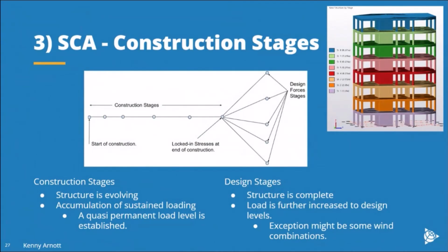So starting with this concept of construction stages and design stages, which may be unique to our software in that terminology. So the construction stages, got a sort of timeline view here. The construction stages are dealing with the evolution of the structure. So we're building it up floor by floor till we've got the structure complete. And at the end of that construction, we've got a completed structure with some level of load on it. So the structure has been evolving and also the load on the structure is evolving. So we establish what we might call a quasi-permanent load level by the end of construction.